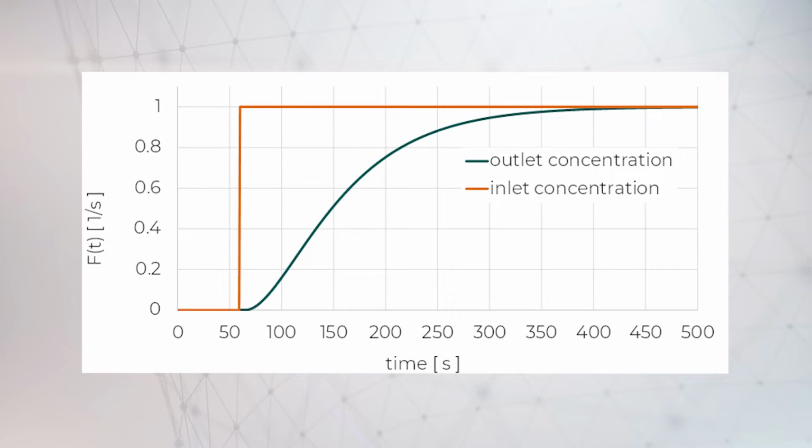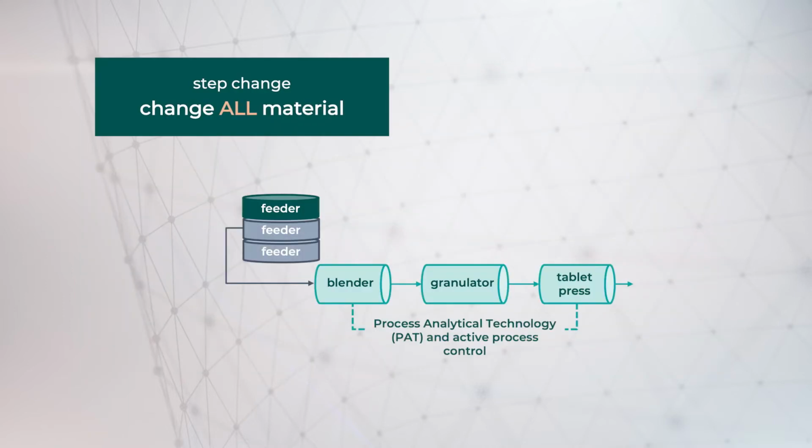The cumulative distribution function would then show you when you have reached the maximum concentration of the substance in your bed at the outlet. The second option is that instead of still feeding 3 materials, you would change to one single substance that would substitute for all 3 substances and act as a tracer. You can imagine that such a drastic change in material can easily lead to a change in the flow pattern.